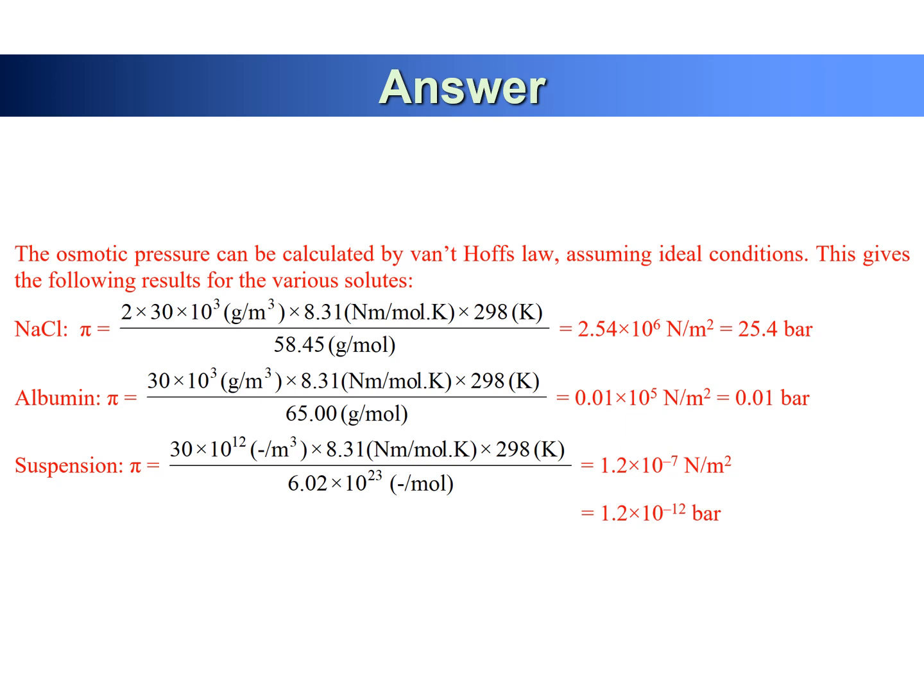The other way is you put in all the detailed salt concentrations and utilize software, and it automatically calculates your osmotic pressure in terms of concentration and different species. That's the way we can calculate the osmotic pressure for your seawater desalination plant design.